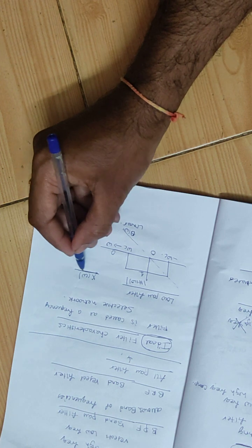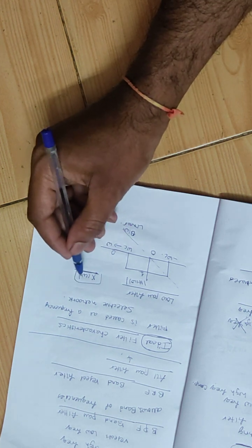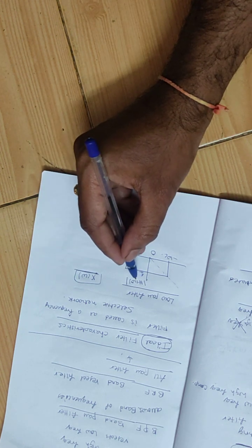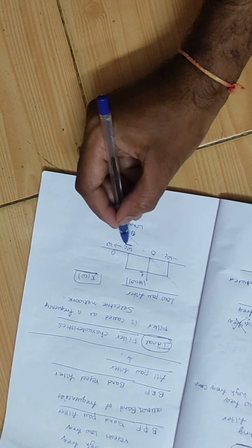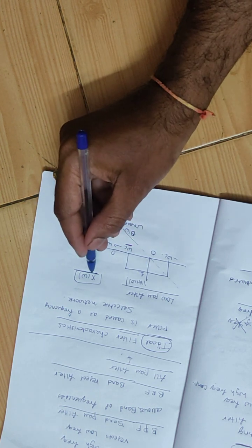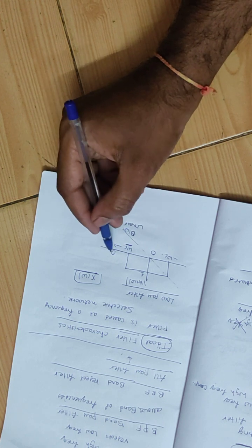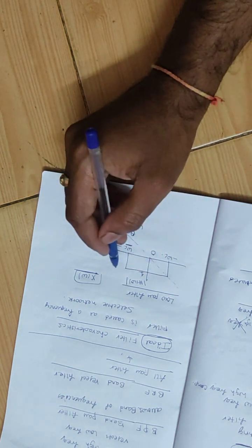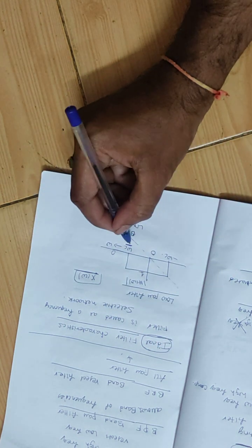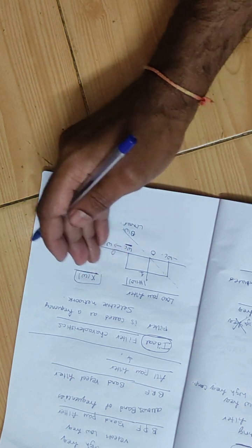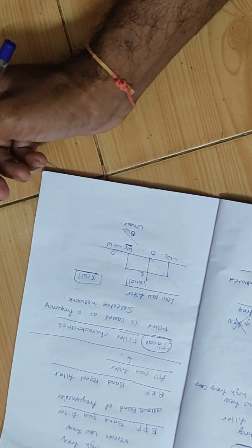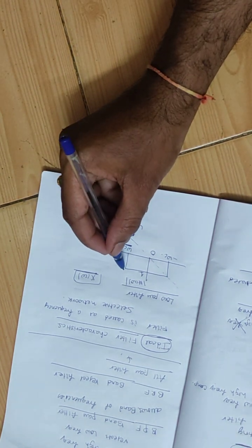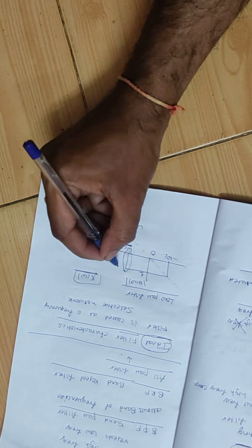Okay, so the spectral density function of X of omega, that means the frequency domain representation of X of omega, would be affected by this H of omega. All the frequency components up to omega c are multiplied with 1. All the frequency components in the X of omega beyond omega c are multiplied with the 0. So that means it's a low pass filter. It is allowing the low frequency components up to this cutoff frequency, and it is rejecting all the frequencies beyond omega c. Okay, so this has a sharp cutoff.